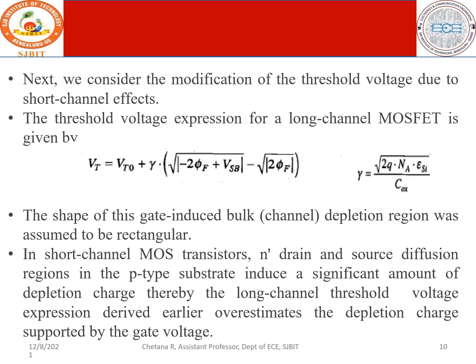Normally in a transistor, the channel formed is assumed to be rectangular. That means the length is L and the width is W. But in a short channel, you have the two terminals, drain and the source, and there is depletion occurring, and this depletion is resulting in the change in the threshold voltage. So how it is going to vary, we will see this.